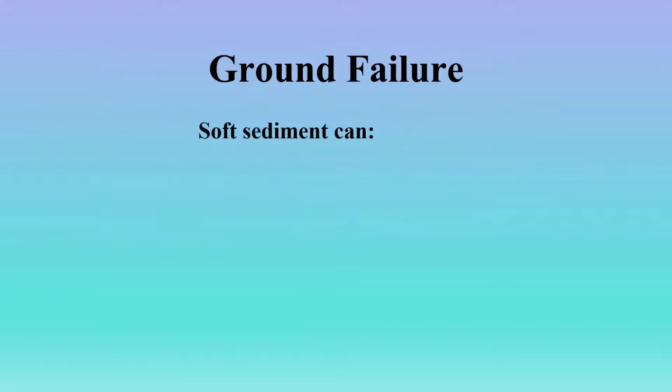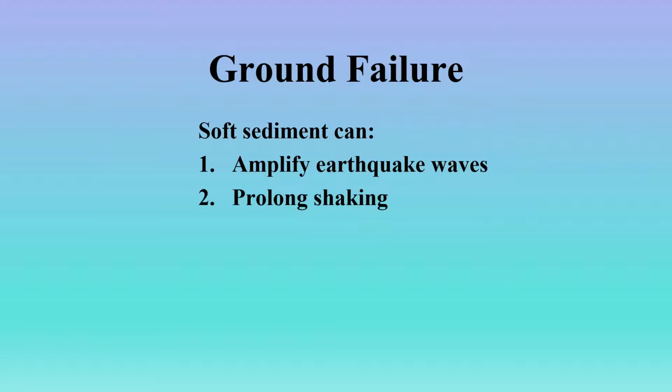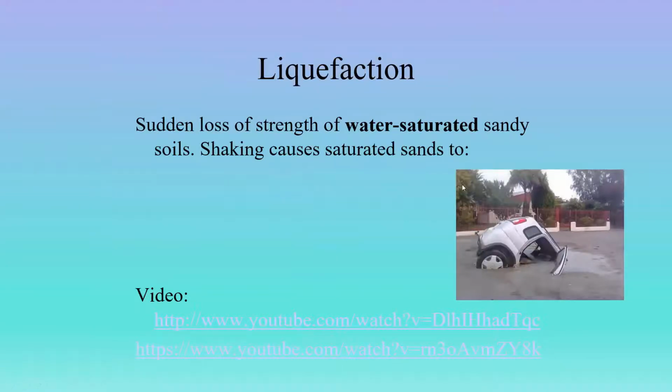Ground failure. Ground failing happens in areas where we get those soft sediments. Not only can it amplify and intensify the earthquake waves, it can also prolong them, right? But it also can cause the failure of the ground in what's called liquefaction, where it basically liquefies the ground. So this is a real picture here on a street in California. This would have been a dirt road or dirt street. If you look it up online, there's a whole series of these cars in this little cul-de-sac that this happened to.